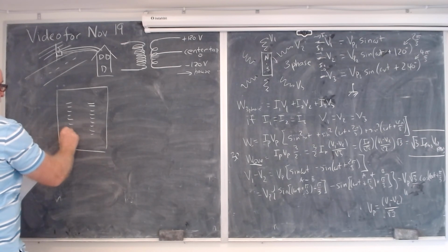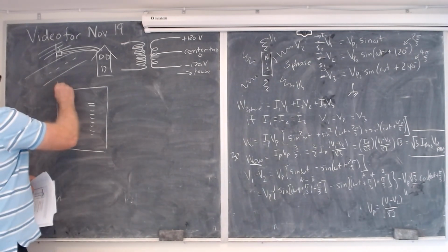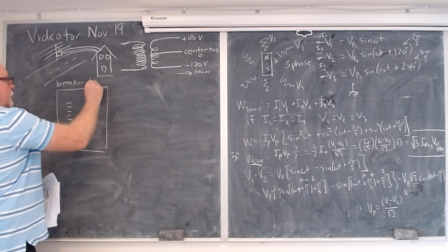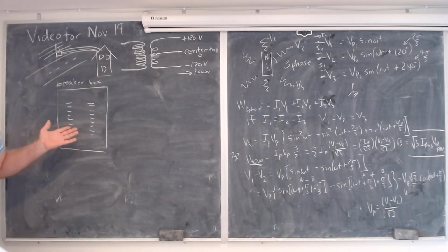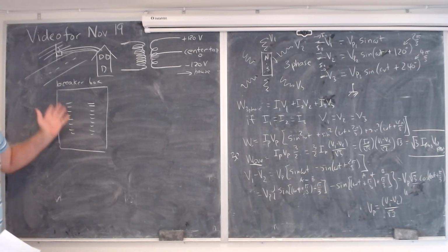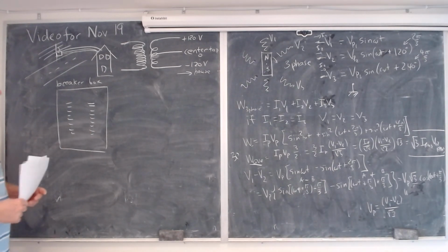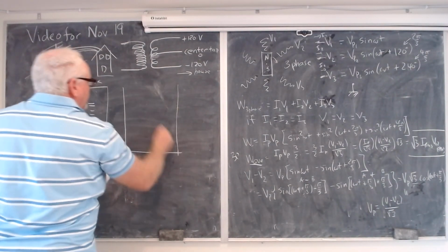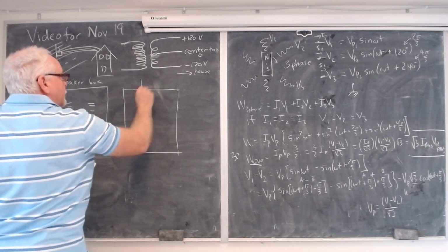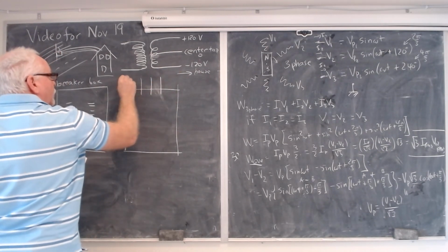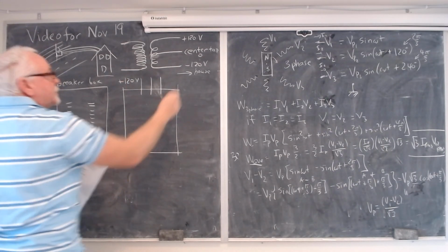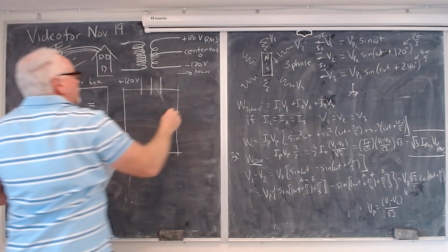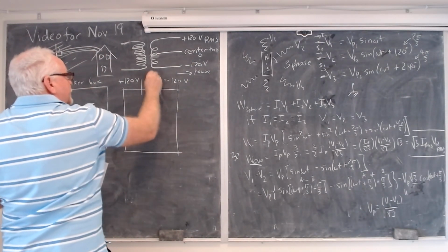you might know of this box. You might know this box because if you hook up something to a circuit and draw too much current, it might trip one of these breakers because it's only rated to a certain current. It's designed to do that so that you don't excessively load the system. Now, if you look at the inside of this box, you'll see that those 3 wires come into this box: plus 120 volts, now these are the RMS, by the way, minus 120 volts and 0.